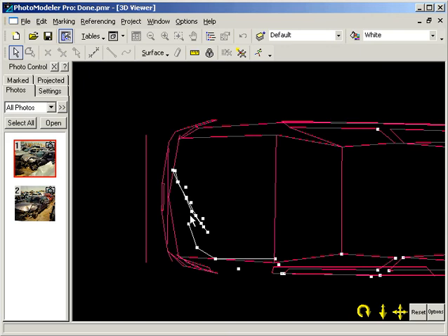If you're using a technique where you want equally spaced measurements on your crush profile for doing your delta V calculations, it might be easier to export the crush project data to your CAD program in the form of a 2D DXF file. You can compare with a 2D DXF profile of the exemplar vehicle and do the equally spaced measurements within the CAD program, or even on a plotted drawing.